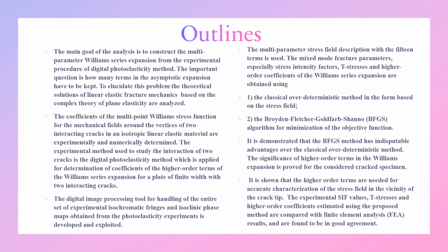The experimental method used here is the digital photoelasticity method, which is applied for determination of coefficients of the higher order terms of the Williams series expansion for a plate with two interacting cracks for a plate of finite width.